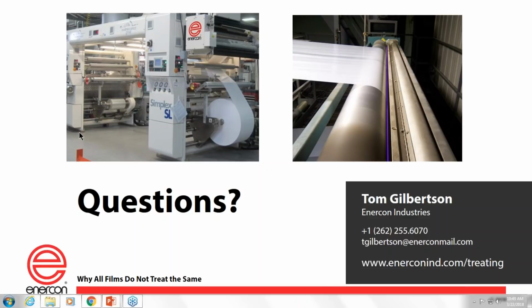So bump treating refers to taking a 36 or 38 dyne pre-treated material and just bumping it 2 to 4 dynes. And so the power required to do that typically would be small, low. Depending on the speed and the width, the exact details of the application, you might only require something like a 5 kilowatt power supply or less, versus on a blown film line, for example, when they made the film, that material being what it is may have required a 10 kilowatt power supply or something, based on their running conditions. So that's kind of the difference when you talk about bump treaters.